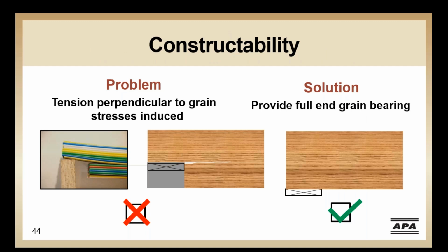When the bottom of the beam is notched, particularly at the end where the shear is the greatest, the beam wants to split. Recall how we discussed that the wood fibers are similar to straws. We can see in the photo on the left that the straws want to split apart at the bearing. Tension side notches are limited to 10% of the depth of the beam.